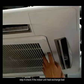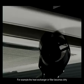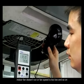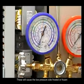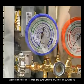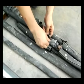Step 4. Check if the indoor unit heat exchange is bad. For example, the heat exchanger or filter becomes dirty, resistance of air outlet is too big, indoor fan doesn't run, or fan speed is too low, and so on. These will cause the low pressure side frosted or frozen. The suction pressure is lower and lower until the low pressure switch acts. If it exists, please check and exclude the malfunction.